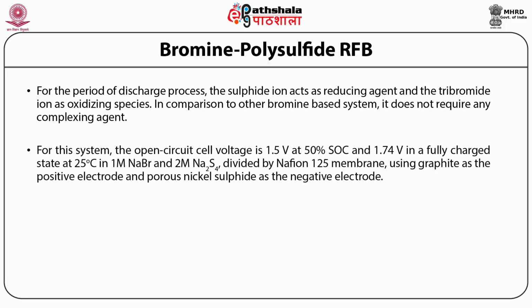For this system, the open circuit voltage is 1.5 volts at 50% SOC and 1.74 volts in a fully charged state at 25 degrees Celsius, in 1 molar NaBr and 2 molar Na2S4 divided by a Nafion 125 membrane, using graphite as the positive electrode and porous nickel sulfide as the negative electrode.